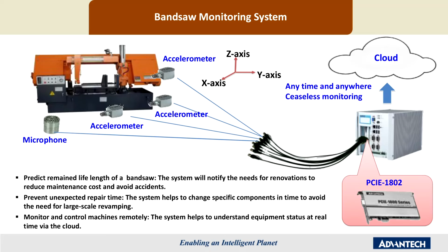Compared with the metal loss, machine downtime is much more critical to the factory and decreases productivity. Therefore, machine health monitoring is helpful to prevent this potential loss, increase factory productivity, and reduce unexpected material loss and machine downtime. Typically, an accelerometer and a microphone will be installed on the bandsaw and the motor respectively to monitor the vibration and the sound frequency generated by the machine in operation.